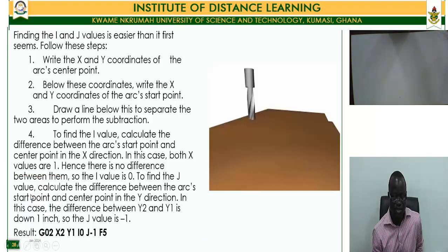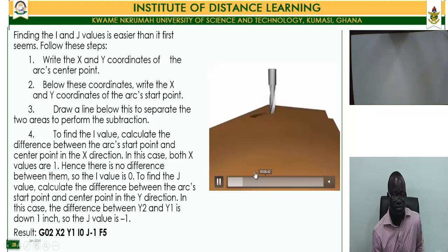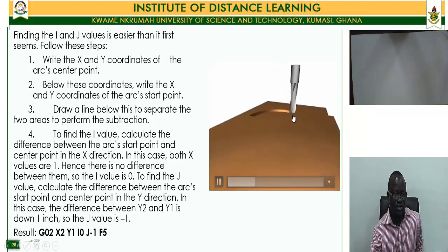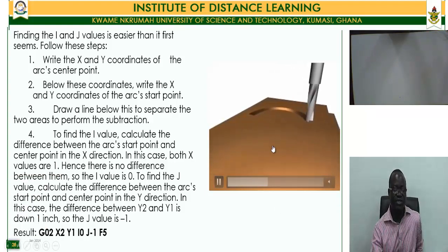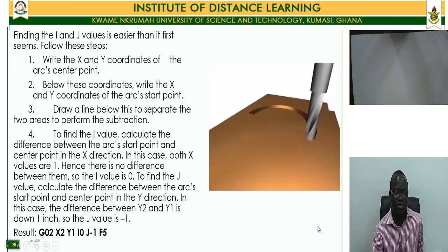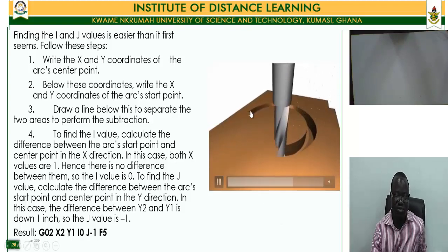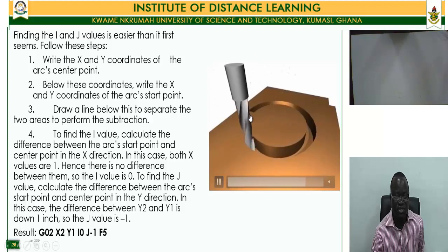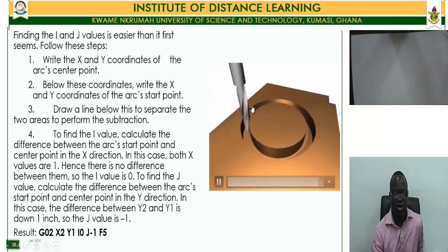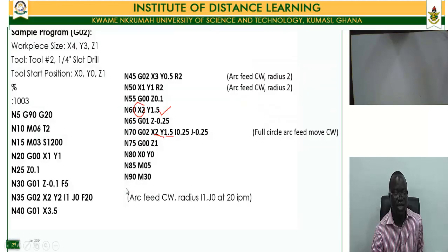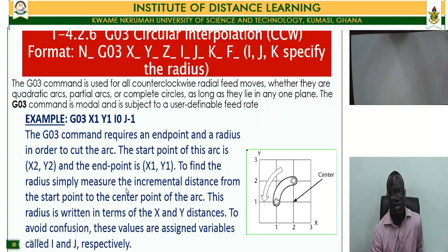so let's look at the next command, which is the G03, which is just like the G02, but this time this is a circular interpolation in the counterclockwise direction. That is, we are looking at it in the counterclockwise direction this way. Now, the same way, you give the G03 command and you put the final coordinate designations, that is an x1, a y1.